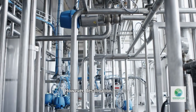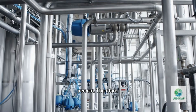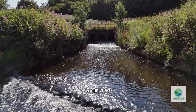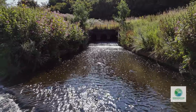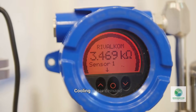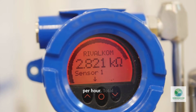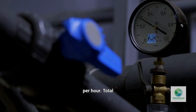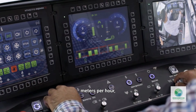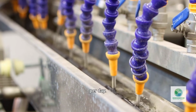However, desalination recovery rate is 45%. Therefore, seawater intake required for processed water equals 17.3 divided by 0.45, which equals 38.4 cubic meters per hour. Cooling water demand may add approximately 68.8 cubic meters per hour. Total seawater intake therefore equals 107 cubic meters per hour, or 2,573 cubic meters per day.